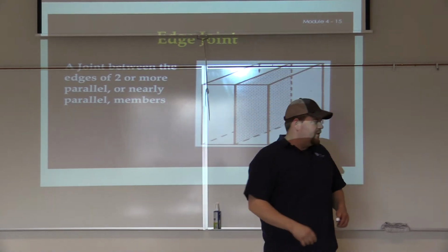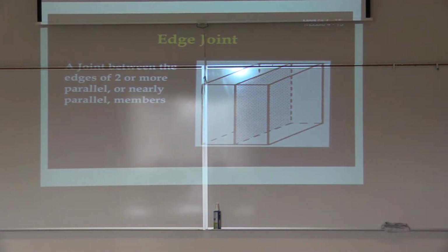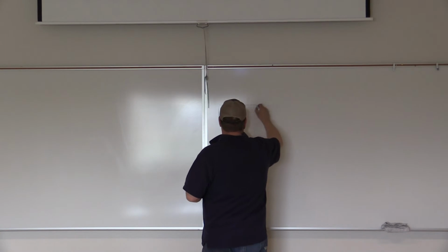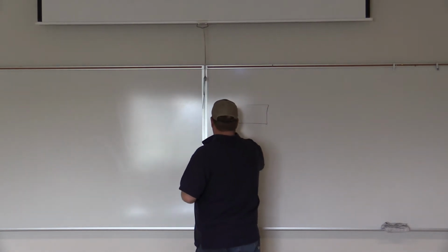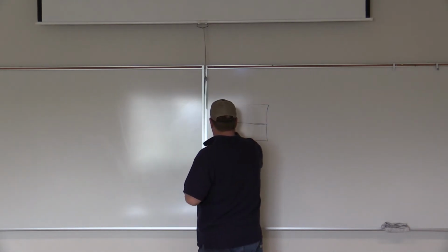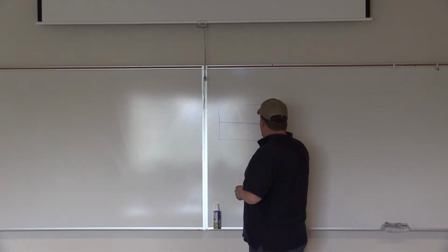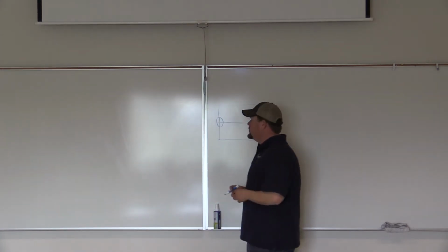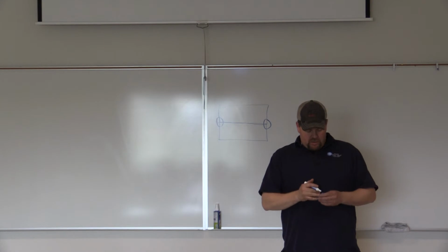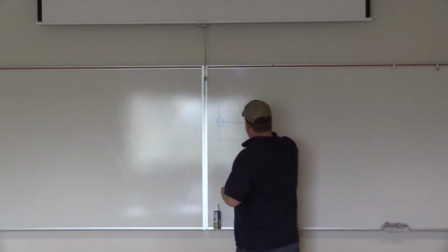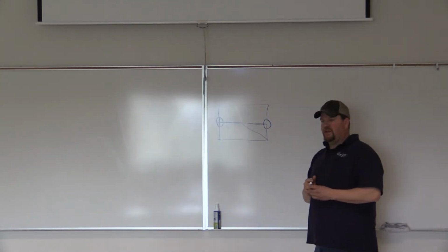A good example of this, I want you to think of road construction equipment. Most stuff that we're going to use, we would put a weld here all the way around the surface. It's only designed to penetrate, say, 1/8 to 1/4 of an inch, okay? Doesn't need to be a full joint preparation. We don't want that whole thing to be solid at this point.